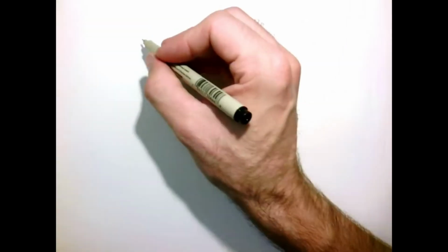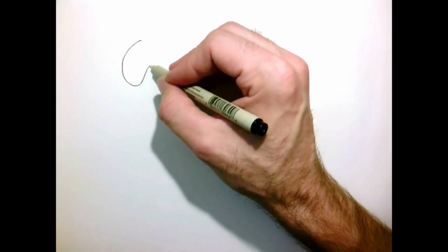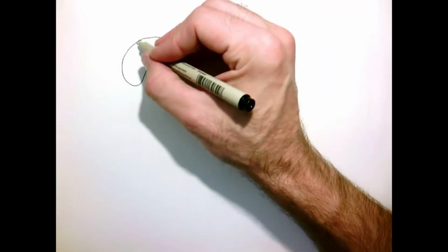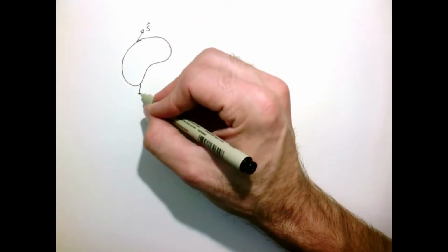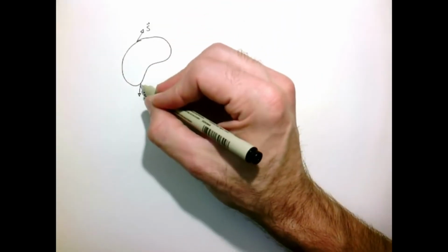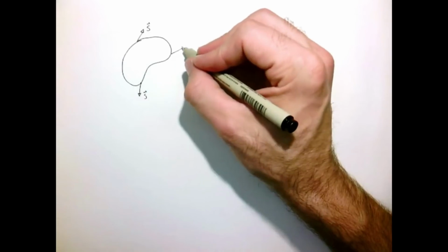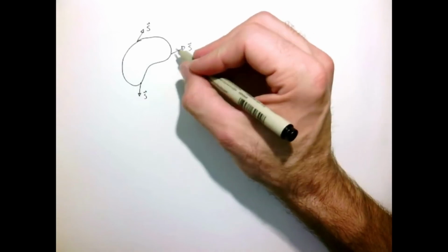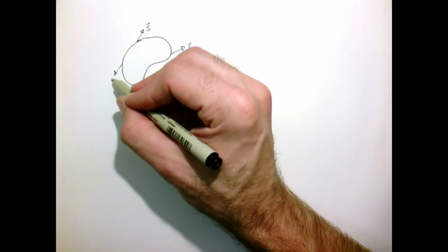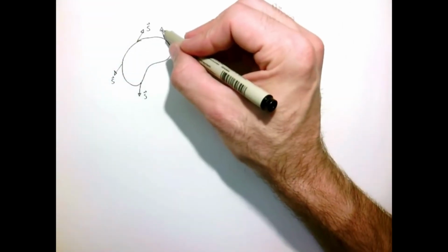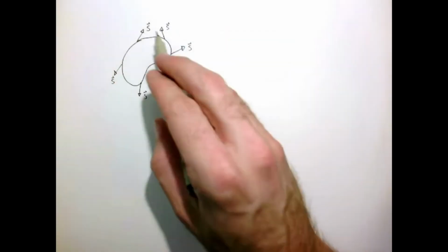So let's see how we might use the stress tensor in our formulation for fluid mechanics. So if we have our arbitrary volume, a potato, and if we imagine everywhere along the surface of this thing, we can go to a point and we can define a stress vector. So this is the force per unit area that's acting locally at that point. And for whatever reason, it could be different all over the object, so it just changes as we go around.